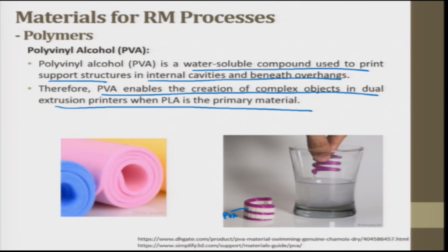So there are certain benefits. It is a great water dissolvable support material. No very special solvents are required, no additional hardware is required, but these properties also bring certain limitations, such as it is moisture sensitive. It has to be kept in airtight storage containers. Then there are greater chances of clogging in the nozzle if it is left hot when not extruding. It is also an expensive material. So these are certain properties of this material.